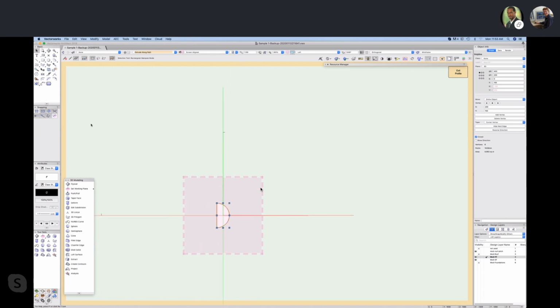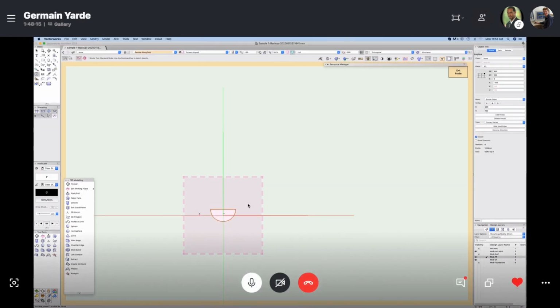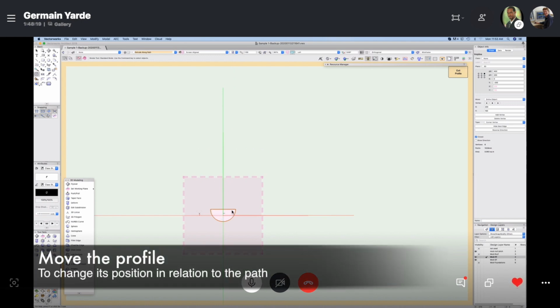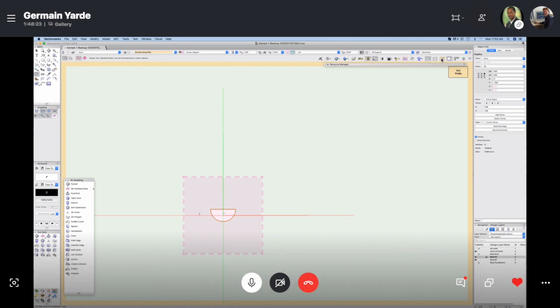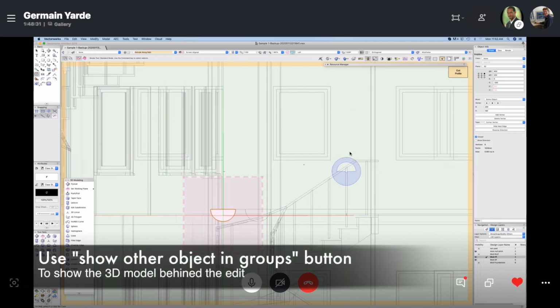So if you can do Command L a couple of times and flip it round, yeah, that'll do. Well done. Command L, you're very right. Let's try this instead. And again, and again. Now the other thing is, you've got to move the top corner of it one way or the other. Okay, now you might want to turn the model back on in the background, so that little eye icon up in the top right corner. Yeah, that's it.